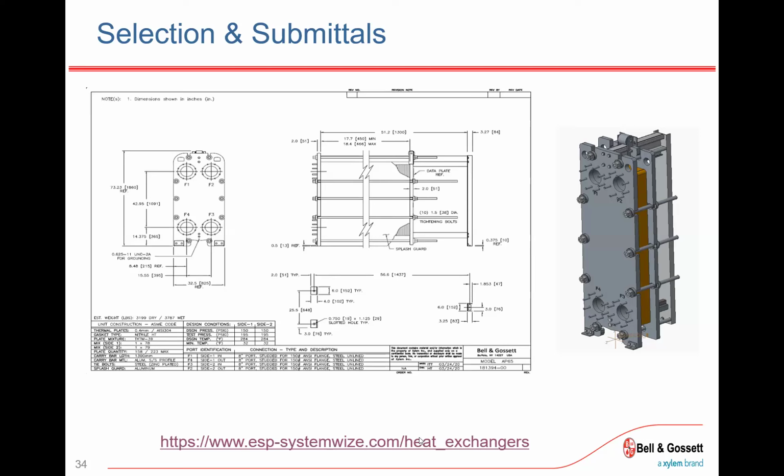And lesson learned: here in Massachusetts, we might think that we have everything covered, and anything that's code here is probably more strict than everywhere else. Well, sometimes other states have these really progressive or greater safety codes. So yeah, I think all those heat exchangers were ordered and had to be reordered under double wall. I imagine it was in the high tens of thousands range. But nobody was aware of what that local code was. So just an example of codes are important for wherever you're doing business.